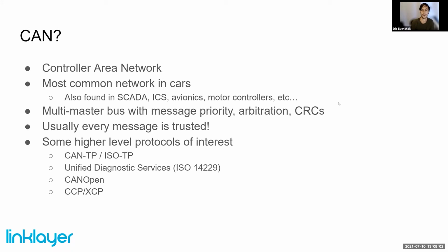It'll get you some fault codes out of the device or out of the engine controller. You can clear fault codes and read some data. Unified Diagnostic Services is a whole bunch of extensions to that. They are proprietary. They're specific to whatever manufacturer you're looking at. And they'll let you do all sorts of stuff.